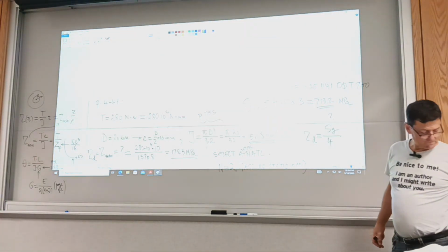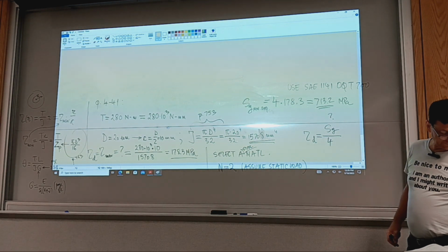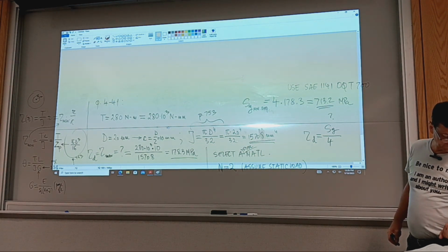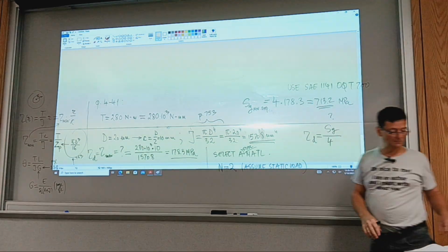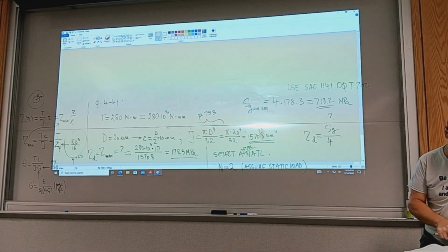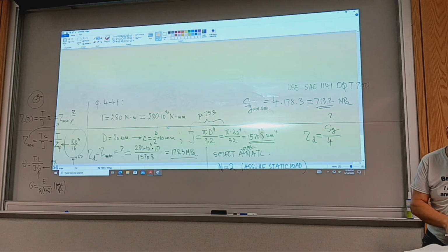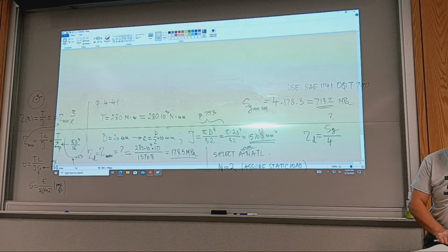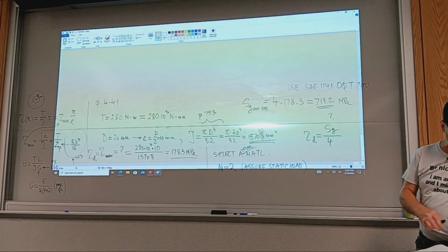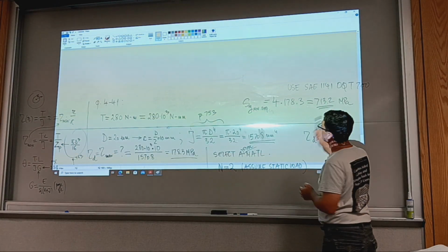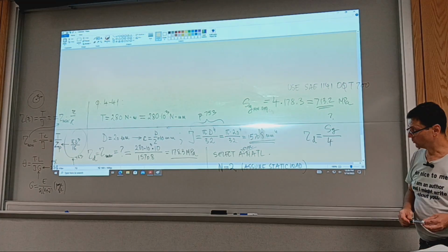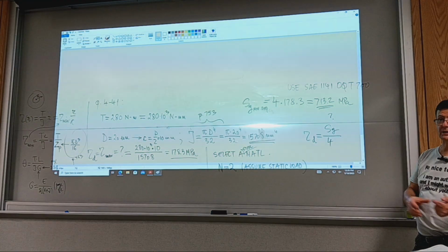In terms of, for us, anything like in the 800 range is fine. Maybe read more about the difference between oil quench and temper 900 and 700. So 700 might be a more rapid cooling, and not all parts may end up that strong as listed there. More variability in the process. But yeah, this was it.